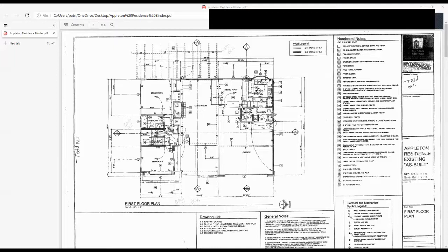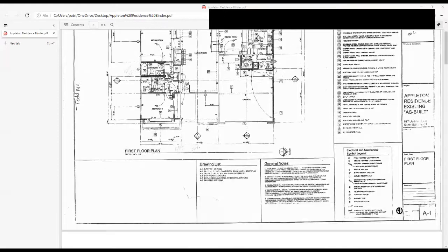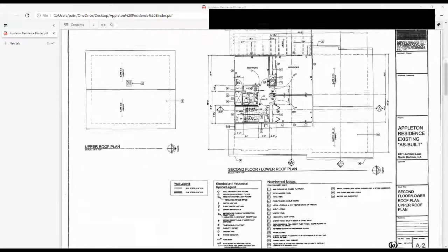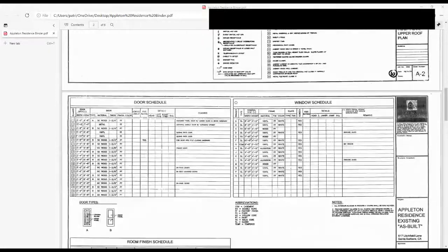So Bill Dang, you've got these in your Canvas file. So you got a floor plan, second floor plan, door schedule. Let's talk about schedules too while we're at it. It's the one print we haven't talked about. At minimal, they're doors and windows. Sometimes they'll be finished material, like baseboard or crown. If the house has a lot of varied finished material, then they'll want to schedule to separate it out and make sure you're getting the right stuff.